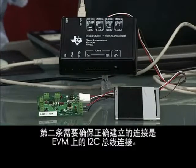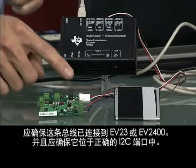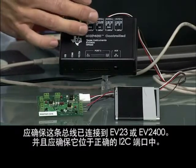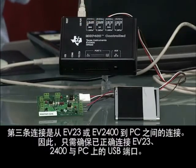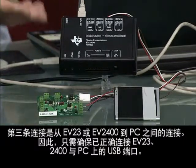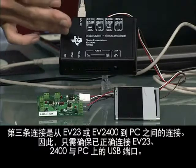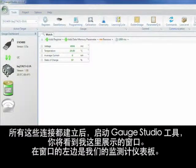The next connection you want to make sure that you have done correctly is the I2C bus on the EVM. You want to make sure that it's connected to your EV2300 or EV2400, and that you have it in the correct I2C port. The third connection is going to be from the EV2300 or EV2400 to your PC. So you just want to make sure that you have the USB port on both the EV2300/2400 and the PC connected properly.